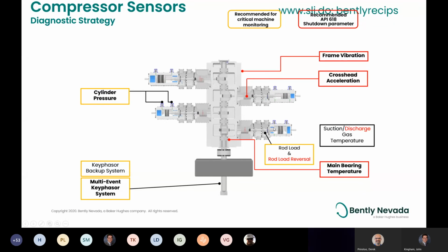We can calculate what the force is at the piston, or at the rod pin. That pin is the weakest part of the system, so that's where we typically want to calculate it. We want to make sure that the stresses are loading and unloading on that pin, because if it's only loaded or only unloaded, it's going to block the hole that feeds it oil. If you don't have oil going to that pin, you'll have metal on metal, and you will have a catastrophic failure shortly.